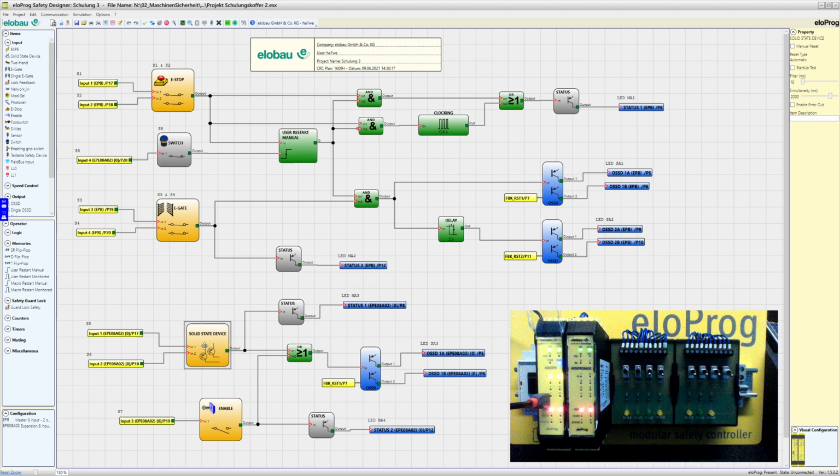Those safety sensors also have OSSD outputs, which are monitoring themselves. Therefore, it's not necessary to have additional monitoring at the inputs, like here with the test pulses. And you can see here at the capabilities, we don't even have the choice to activate test pulses.